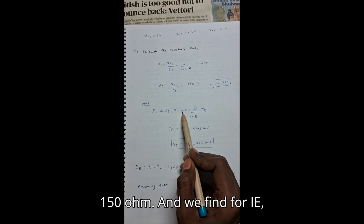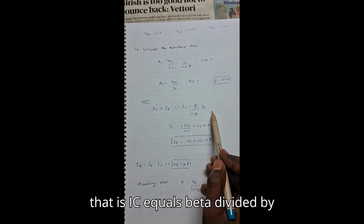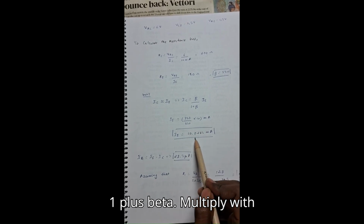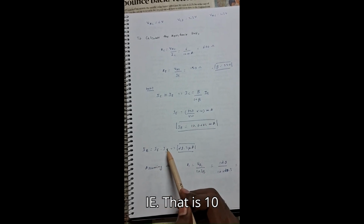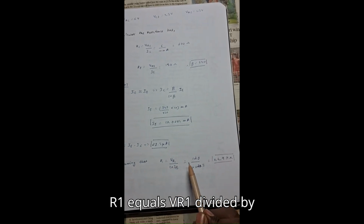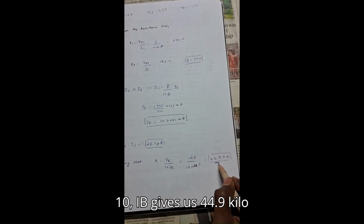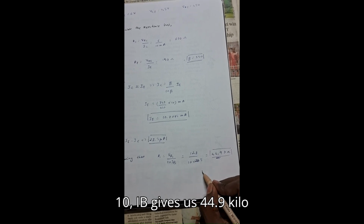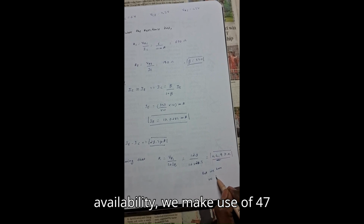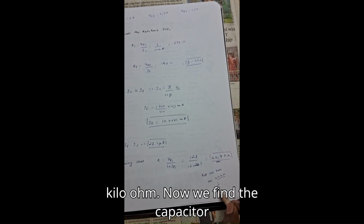And we find IE, where IC equals beta divided by 1 plus beta, multiplied by IE. IB is 10 microampere. Assuming R1 equals VR1 divided by 10 IB, it gives us 44.9 kilo ohm. For approximation and availability, we make use of 47 kilo ohm.